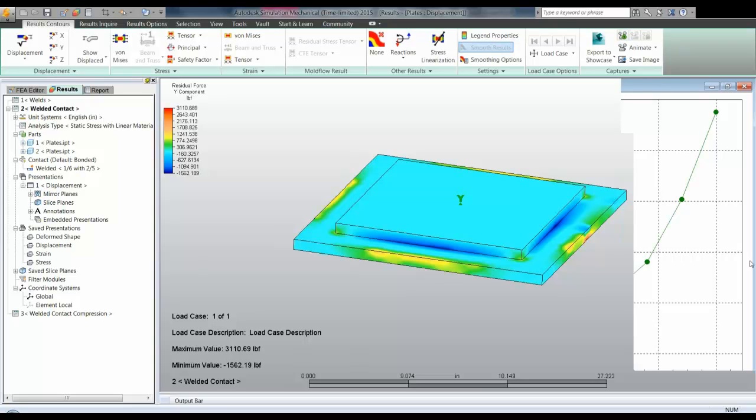With a stitch weld, I'm welding, and then I have a space before the start of the next weld, and it's a way of saving material and effort, so I don't have to have a continuous weld around the periphery. And we can create our model. In this case, James had examples where the weld was continuous, but these welds could be shortened and more numerous, and that would be one way of considering a stitch weld, and that of course would allow you to assess the force per inch or stress or any other result that you think is an important criteria for determining the weld acceptability.